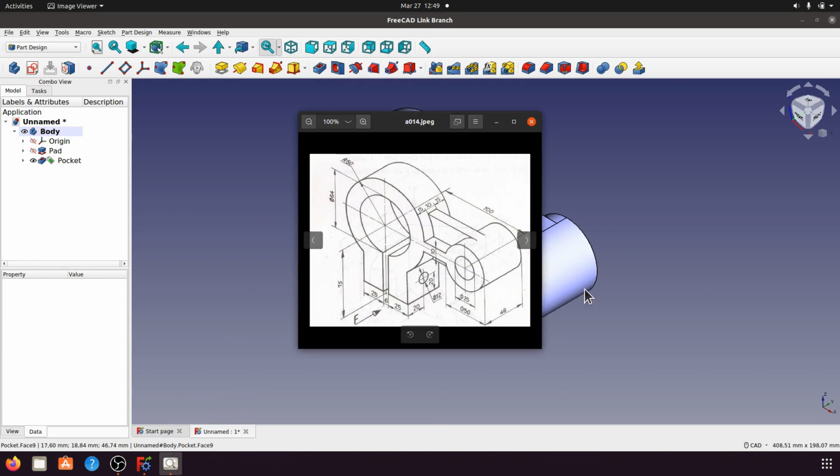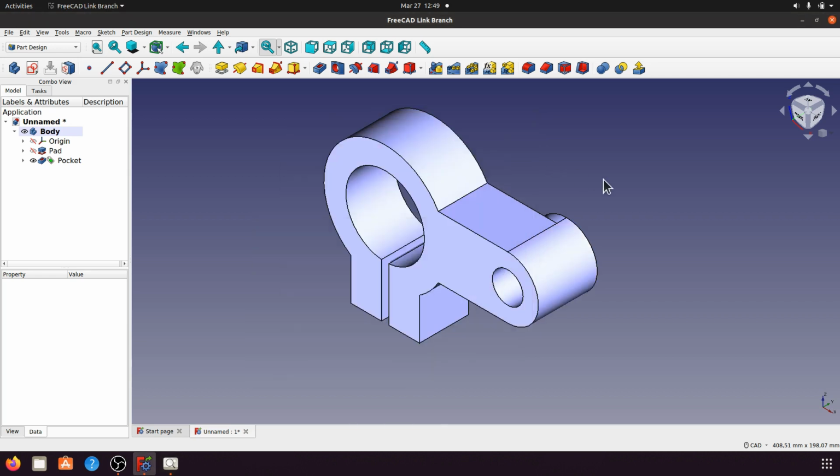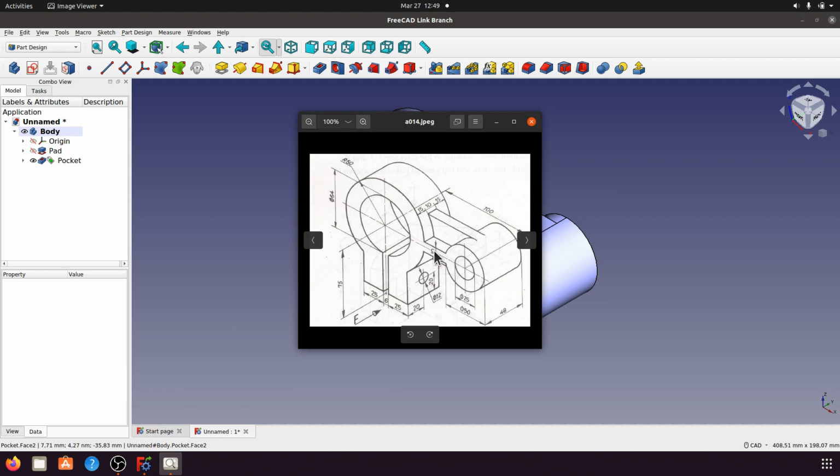Okay, now this is 48 thickness, and then this is 40 millimeter. Now we can create a cut in the support. I check first for the thickness in the middle for 10 millimeter, and then depth cut for 50 millimeter.